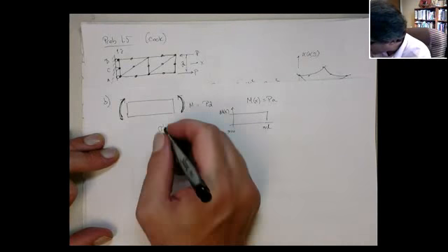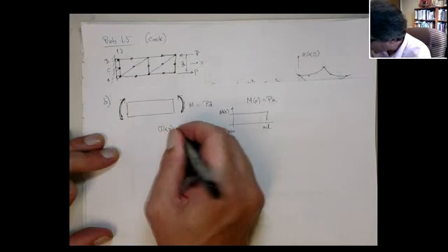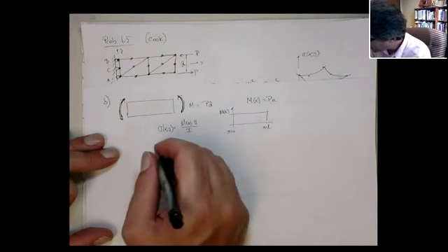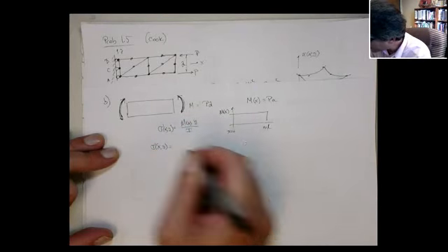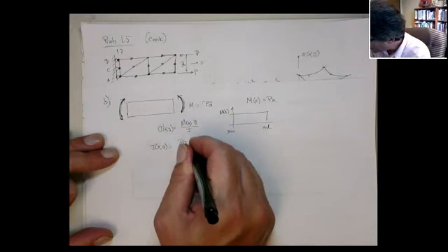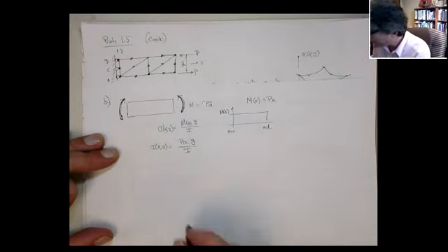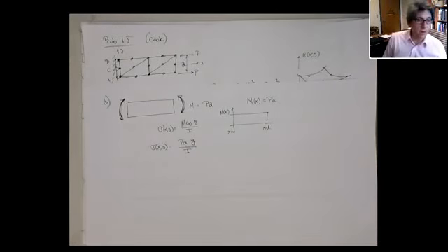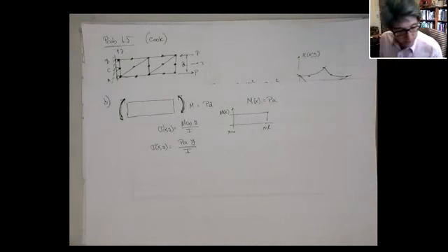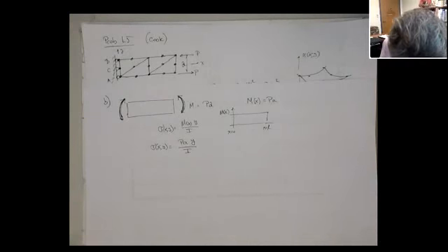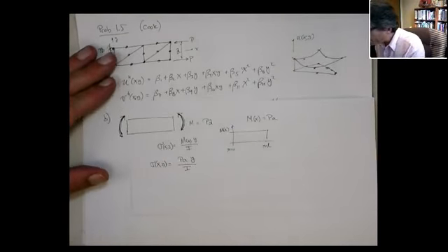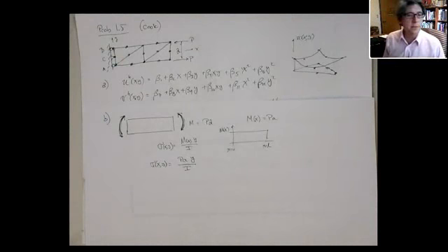And then the stress is a function of x and y. That's the moment, My on I, so that gives us the following: Pa times y over I. So this is a linear polynomial in y. So basically, if you look at something like this, you should be able to reproduce this type of stress field in this element.